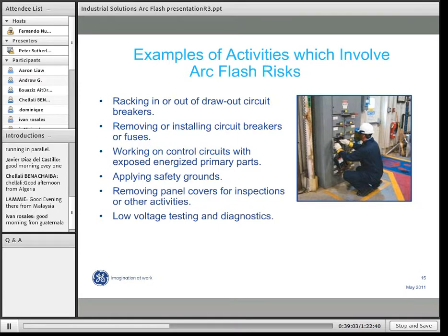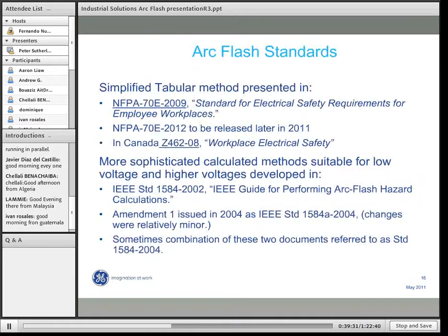and measuring voltage with voltage probes, but in actual fact, it can be extremely hazardous, especially if you consider, for example, that your clamp-on ammeter has an iron core which is exposed while it's open as you're clamping it on, which could draw an arc from some live part. So your safety precautions have to be followed in that case as well. So when you're doing this work,